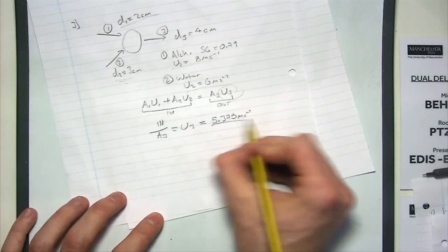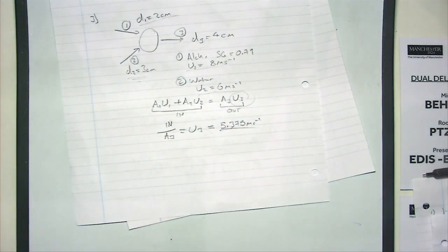Happy? Yeah. Should we multiply by density too? Density, you're looking at the volumetric flow rate. The volumetric flow rate tells you, well, we're saying that there's continuity because the fluids are incompressible, right? So there's no extra space being generated. And you can assume that this whole system is full.